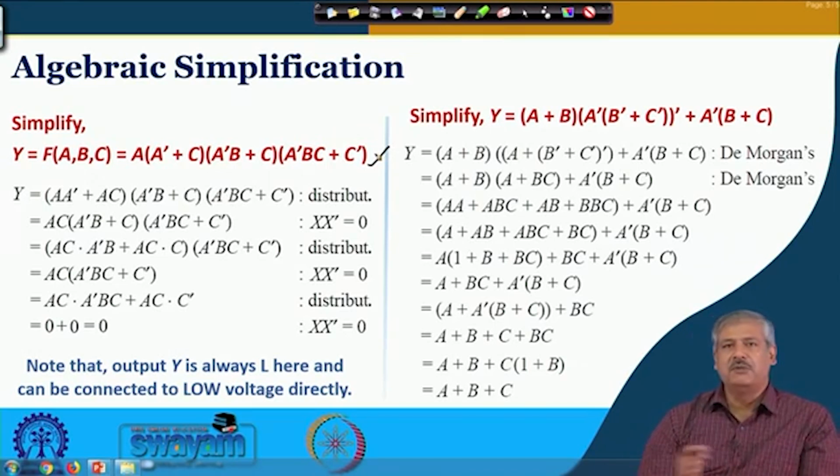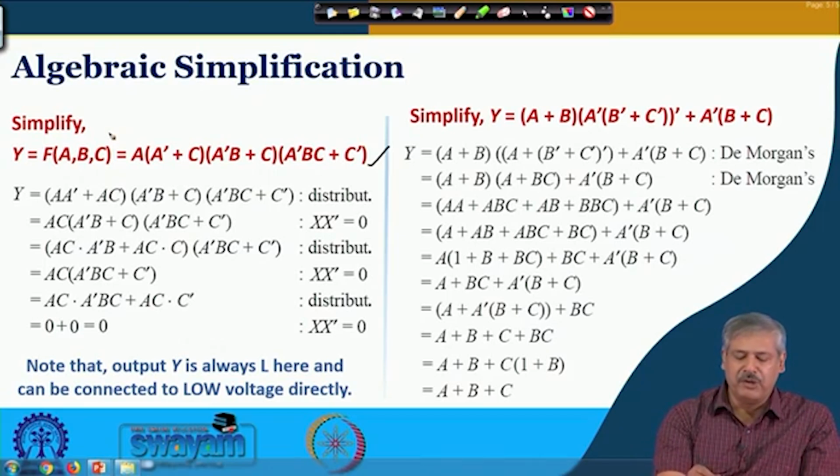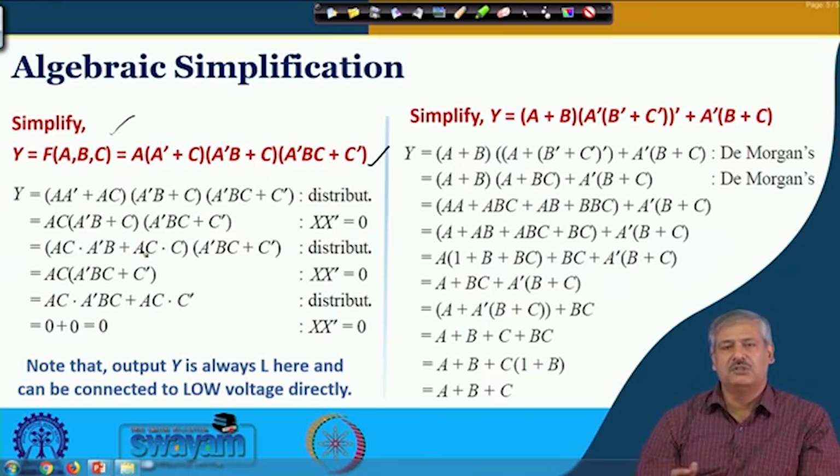So, we can go for direct implementation of this, the way we have just seen how a Boolean expression can be realized in the form of hardware. We can have a NOT gate to realize C prime, then another NOT gate to realize A prime from A, then a 3 input AND gate to realize ABC, then this can be ORed with C prime, a 2 input OR gate, and so on and so forth, and ultimately we can arrive at the final circuit, which will provide you a truth table, these 8 rows and the corresponding columns, the output function.